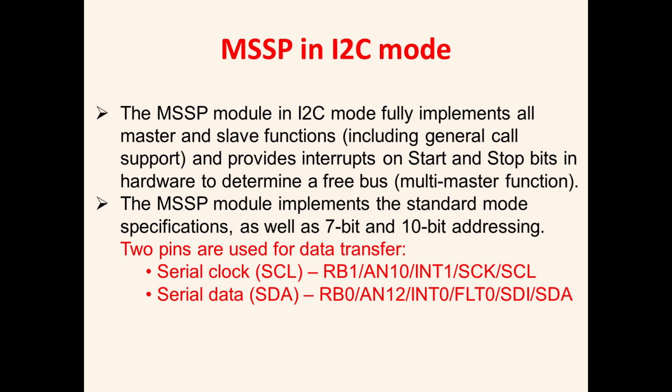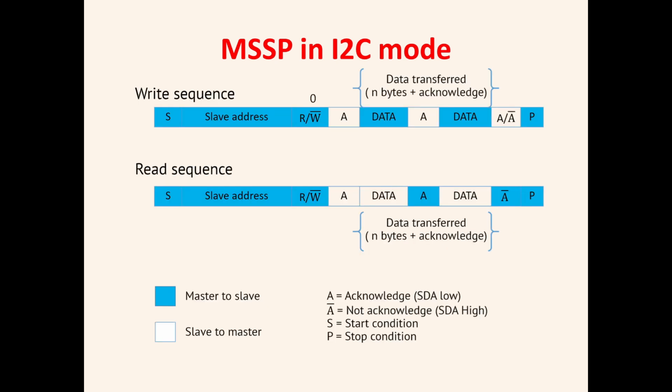After the address acknowledgement, the master will initiate the start bit, and along with that the data will be initiated. After every transmission initiated from the master, your slave has to respond to the master in the form of an acknowledgement. That's why more secure communication is observed in I2C over the years.